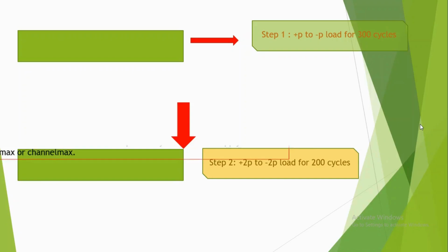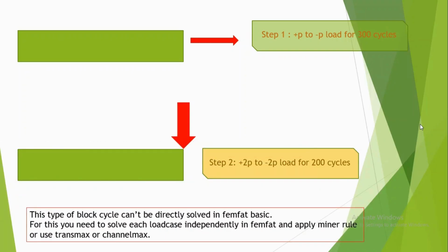Then there is one simple way you can use. This can't be used directly in FEMFAT Basic, but in FEMFAT Basic you can solve each load case independently, like step 1 and step 2, and apply Miner rule in your post processor, or you can directly use TransMax or ChannelMax.